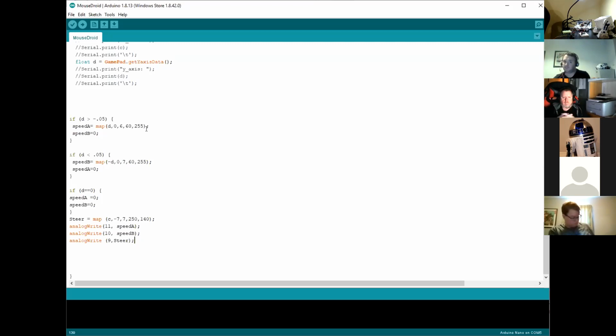That's right. Yeah, absolutely. And then you can use the servo library. The servo library works better because you know that 0 is 0 degrees, 180 is 180, and 90 is bang in the middle. It's a lot more logical. The reason I don't use the servo library on the Nano is it conflicts with the software serial. It's a bit of a nightmare. So I'm putting signals straight out to the PWM, which means I've found those two figures really just by trial and error.